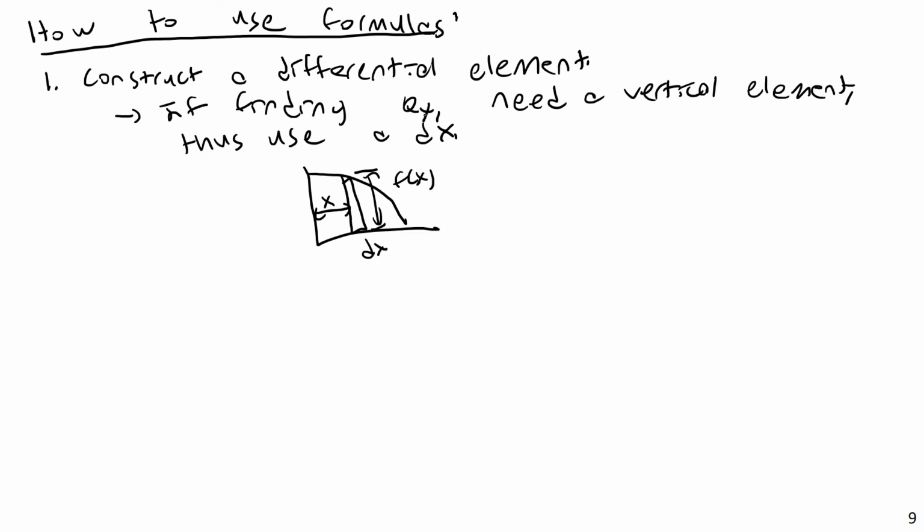And again, it's important to realize that qy describes the integration of area, basically asking how much mass we have, how far from the y-axis. And that is why we use the x-coordinate with this, because knowing how much area you have, how far from the y-axis, will allow you to determine the x-coordinate of the center of mass, or in this case, the center of area, the centroid.